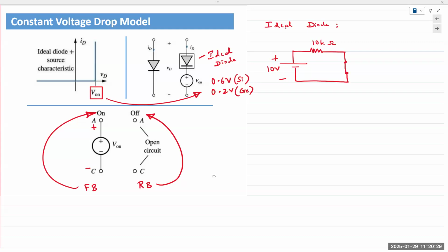And now, circuit analysis techniques. We wish to find the current through the diode and or the voltage across that diode. The verification for both the ideal and constant voltage models would be when we calculate our voltages and currents, and then match them with our assumptions and see if our assumptions hold true.